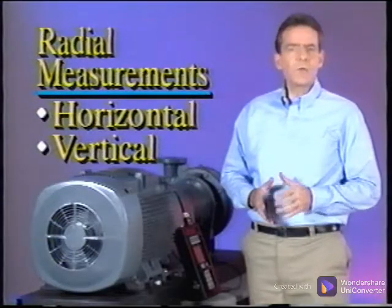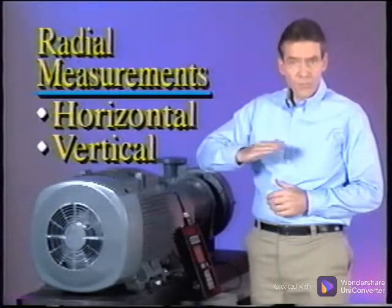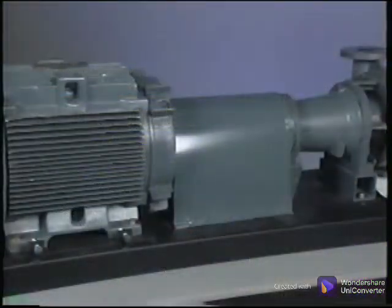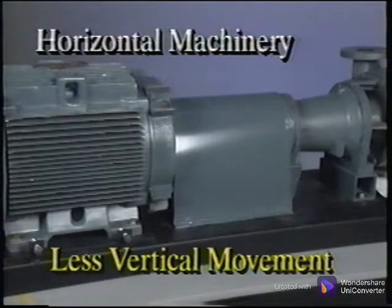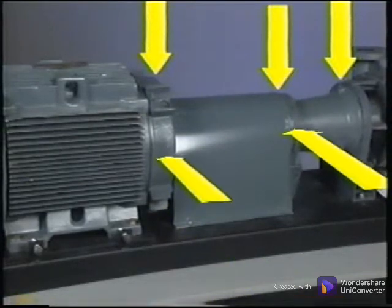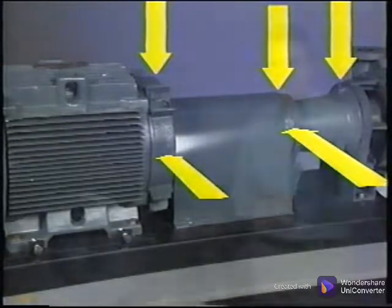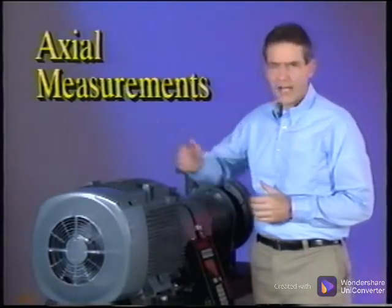These radial readings will give the analyst an idea of how the machine is moving up and down as well as side to side. For horizontal machinery such as this, where the mounting is at the bottom, we typically would expect less movement up and down because it is limited by the mounting. The analyst compares these vertical readings to the horizontal readings to check for problems, such as a soft foot condition or loose mounts. An axial reading is one which is the same direction as the shaft or axis.